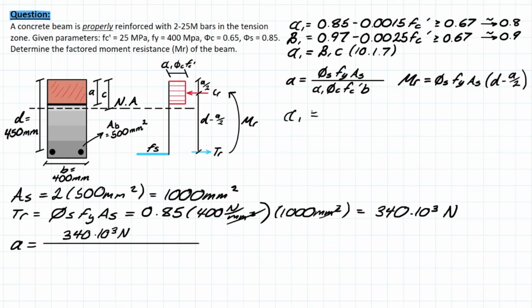It's just using this formula up top, as we discussed, and this is simply a numerical value that we use for the block assumption. Typically, this value is around 0.8. Solving here, we have it equal to 0.81. But for the sake of this problem, I'm just going to take it as 0.8. Normally 0.8 is a fine value to use if you have an fc prime between 25 to 40 MPa, and I'm going to use that assumption here as well.